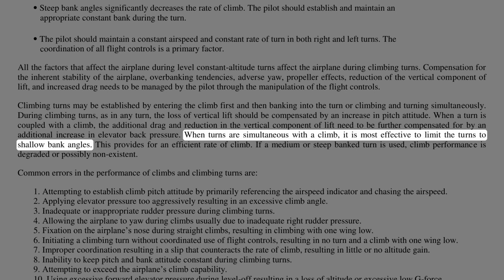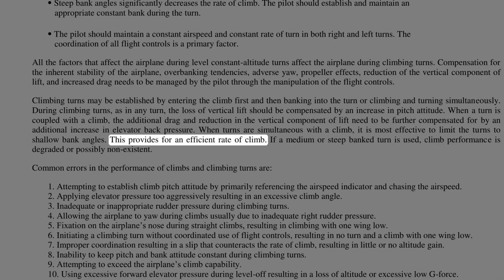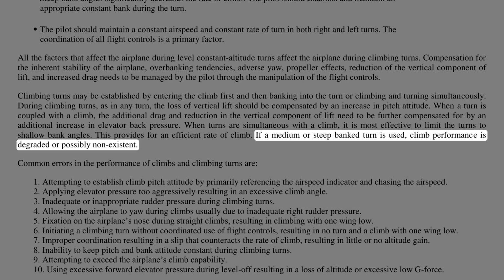When turns are simultaneous with a climb, it is most effective to limit the turns to shallow bank angles. This provides for an efficient rate of climb. If a medium or steep bank turn is used, climb performance is degraded or possibly non-existent.